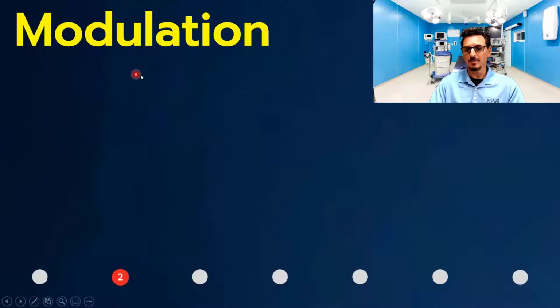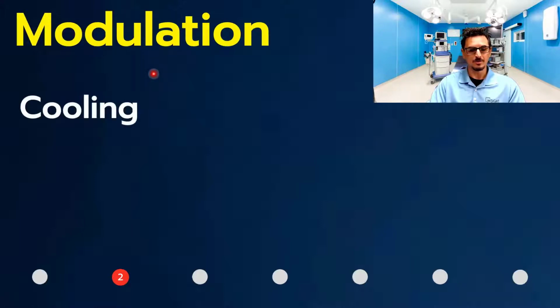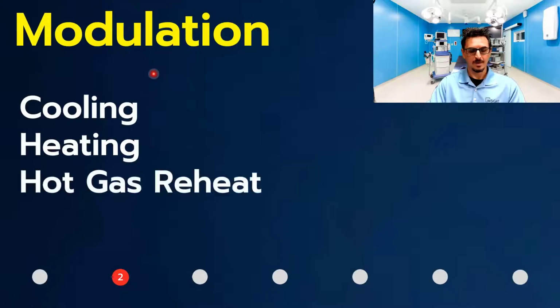All right, modulation, we talked about that before. What are we going to modulate? We're going to modulate the cooling, the heating, and the hot gas reheat in the dehumidification mode. Those are the 3 primary things we're going to modulate.